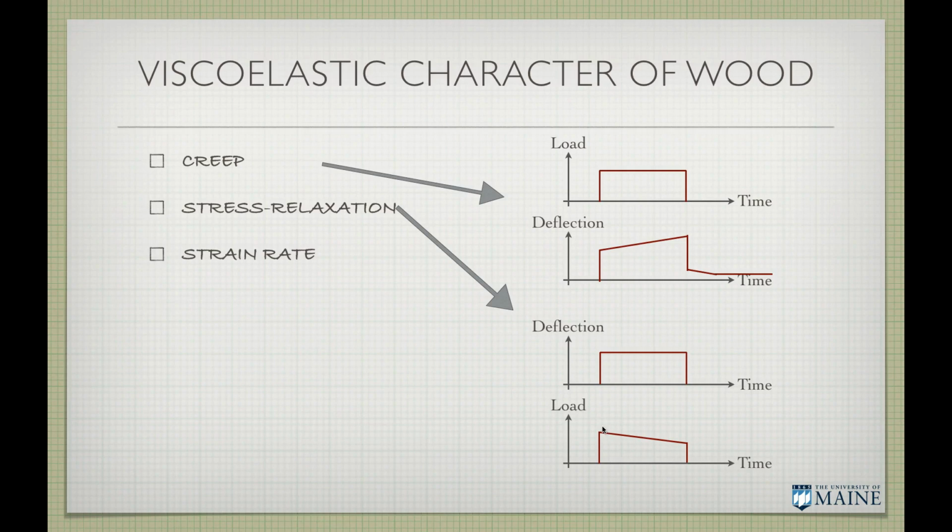The stress, here we talk about load, but you would just divide by area in a uniaxial case to talk about stress. Now the stress would be too low to get a good bond joint. You have to deflect it more to increase your stress to the proper level needed for a good bond joint. If we're gluing pine, what's the kind of compressive stress we often have for gluing solid wood together?